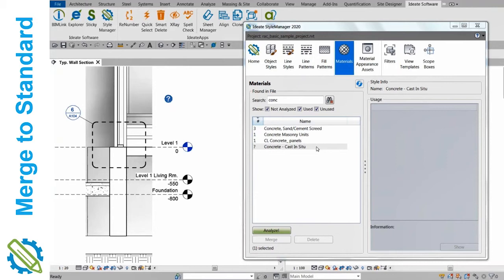It changes everything within the RVT file. If the family is loaded, obviously, and it has the information, then that will be updated. Then what you could do as a next step is, if everything's cleaned up the way you want and the materials are changed, as in this example, you could save off the RVT file on your disk or into your content management system, and then it would have the new updated information.